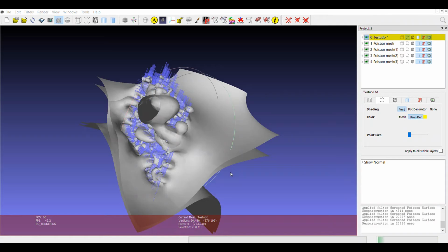After creating my final point cloud in MATLAB, I went to MeshLab to create a 3D printable mesh. To start, I thinned out my point cloud by deleting every third point from the dataset. Then I computed the normals and tinkered with the parameters for a Poisson surface reconstruction. Although I did not generate a very accurate mesh, I think I can attribute it to the gaping hole in the top of Testudo, as well as the error that I was unable to remove from the point cloud.